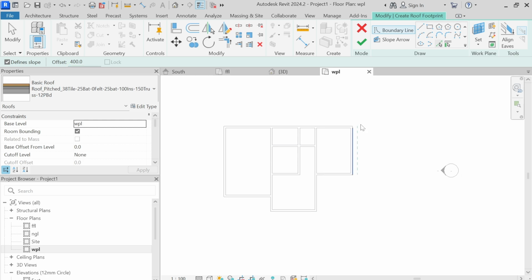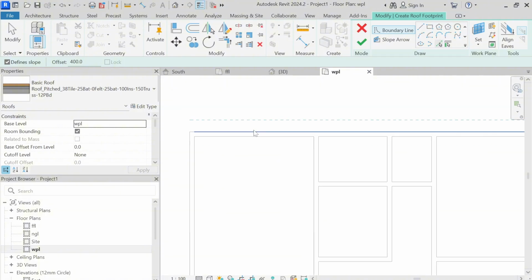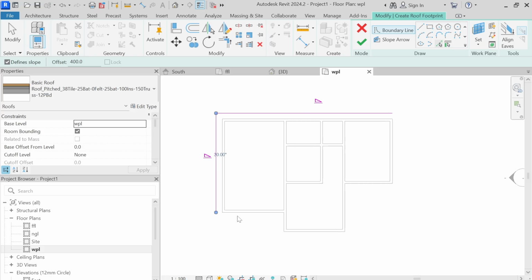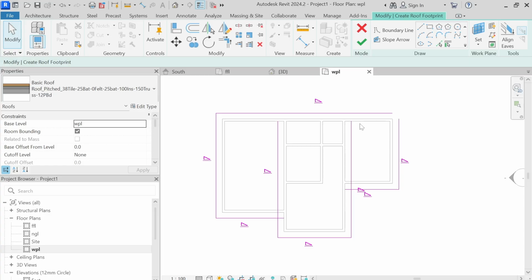Come here. You already click your pick lines. Do not click it again. So on your wall faces, click on your wall face here, click, click, click. Now, what else are you going to do? Same as the slab. Do treatment. Use your trim and extend tool. Sorry, where's my trim and extend tool? There. Trim and extend, trim and extend, trim and extend, trim and extend.